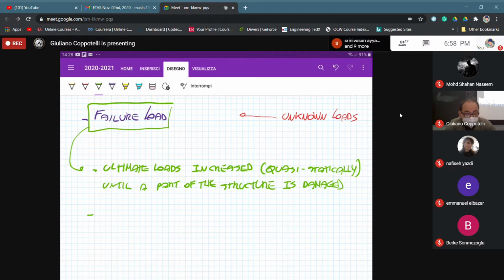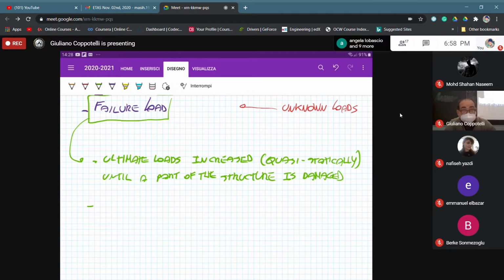And these tests must be carried out at least once in the whole operational life or whatever design, just to see what these failure loads are and if there are some good predictions from numerical modeling, because we would like to have the information of what we call the reserve of strength.